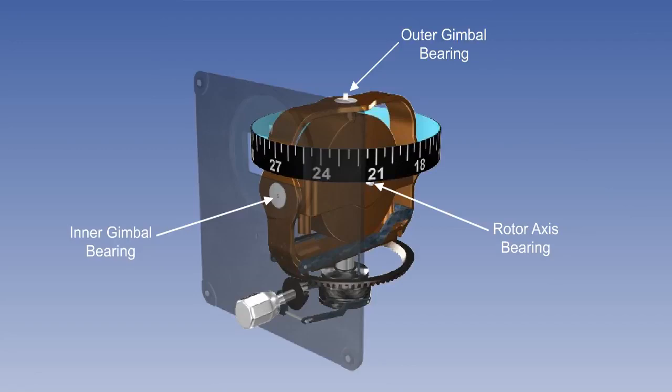The fundamental reason for apparent wander is dealt with in detail in the lesson on gyroscopic theory, and as we have seen, the DGI will be subject to apparent wander from both Earth rotation and transport wander.